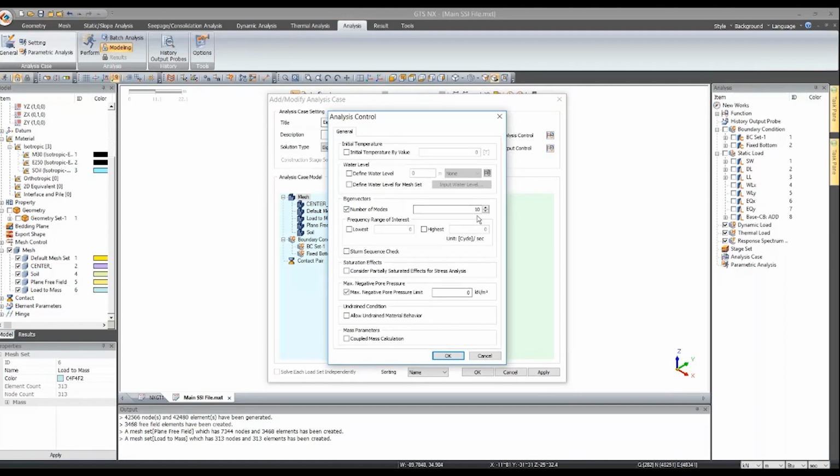As you know, in structures we have different codal provisions in many countries that the mass participation factor should not be less than 90% in case of structures. But here, when you model a soil and structure on the whole, it's very unlikely to find 90% modal participation factor. So we come across participation of 70% or 80% based on the model. If it's close to that, that's good to proceed ahead.